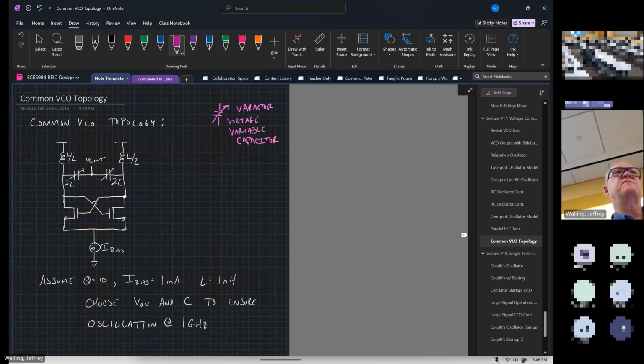How do we make a varactor? MOSFET, yeah. Anything else we might use? It's traditionally a diode. Yeah, any PN junction really works. With a MOSFET, we're not necessarily just using the full depletion region of the PN junction. But if we have a PN junction and a depletion region, we can modulate the thickness of the depletion region, which is effectively changing the thickness of a parallel plate cap. And that makes the voltage variable capacitor.